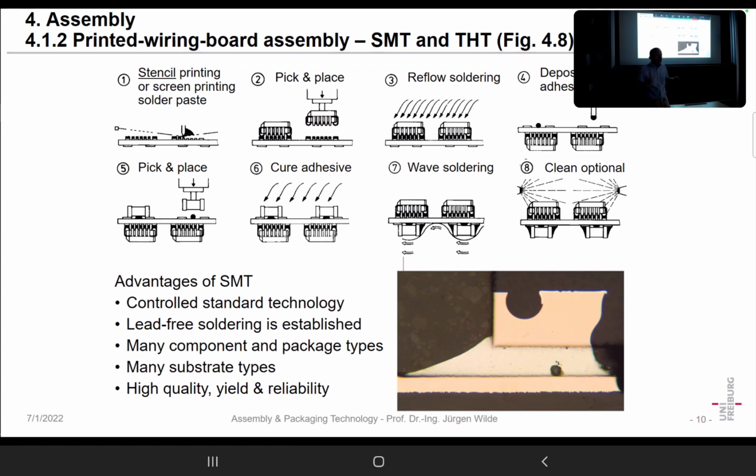So as I said, most pastes we use in assembly and packaging are like toothpaste, yes? You must be able to get a nice pattern of that, but the pattern after the printing must be stable and must not run away, so as not to create defects. On that printed paste, we put the devices.